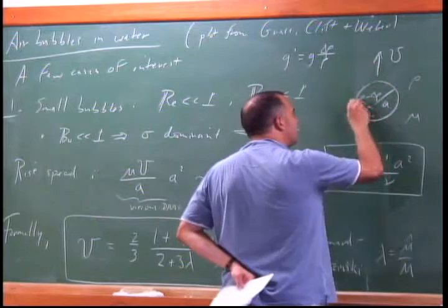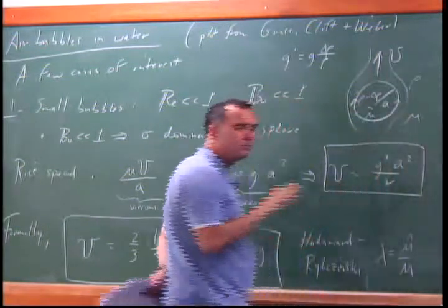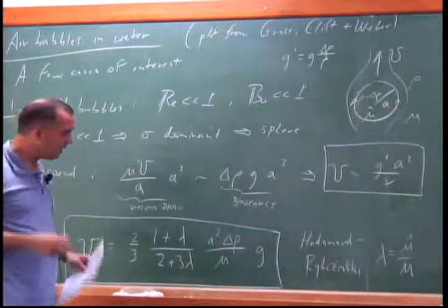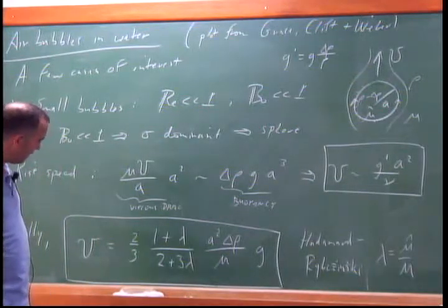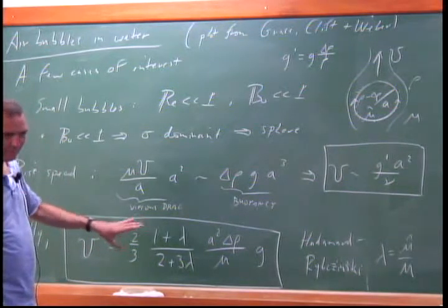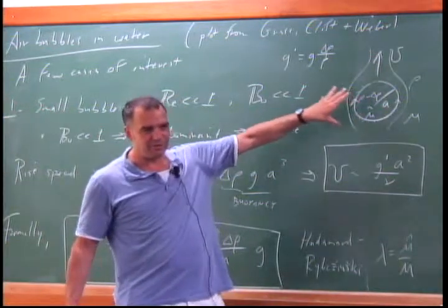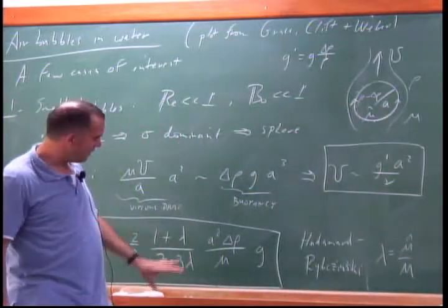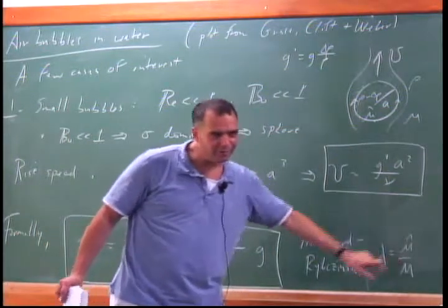Then you have this gradient in surface tension, which rigidifies the surface. So this formula has long been established, but getting the limit of bubbles in the lab is very hard because you always get surfactant effects which act to rigidify the surface, and so you get the result you'd expect where lambda is infinite rather than 0.